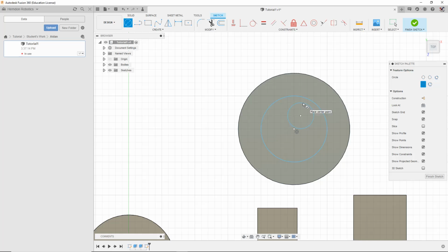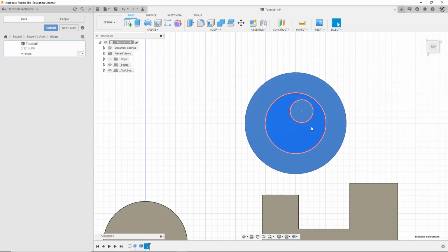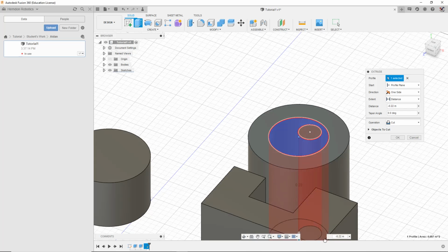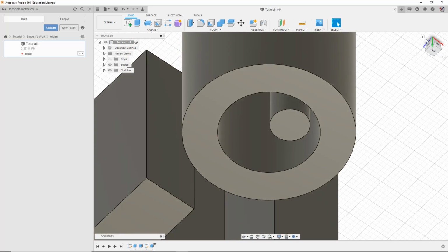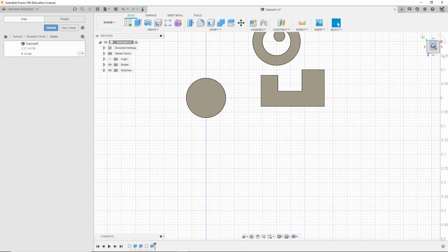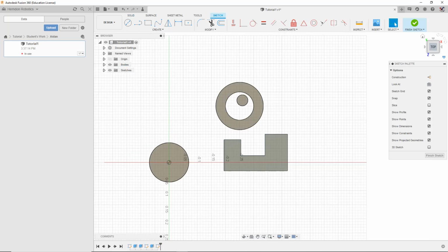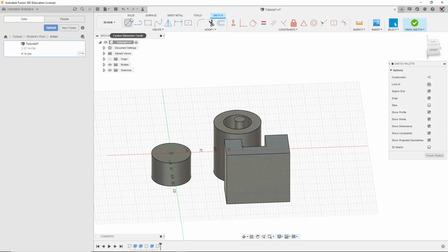So now I can create another circle here, and then let's say their eye is a little weird, so it's offset. And I've created an intersecting one, because now what I can do is select this, then extrude this down, cut it, and this stays where it is, but now we have this little eye in there too. Then that's pretty much all the things, you know. You can kind of select these. It's a little weird making them on a cylinder, but that's pretty much how you create those.